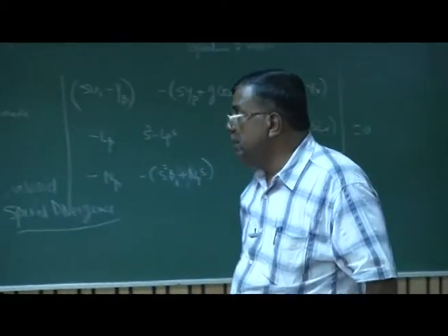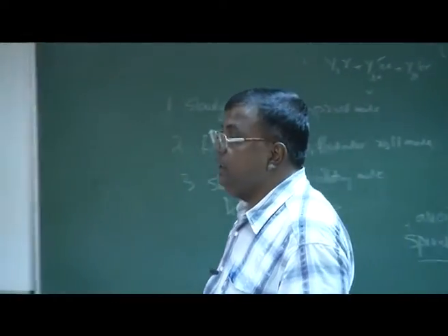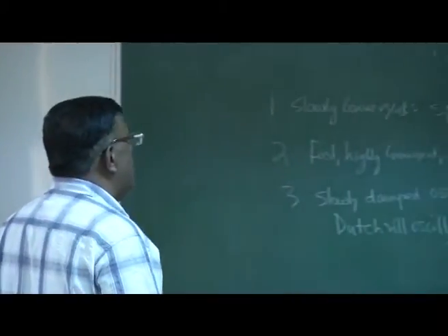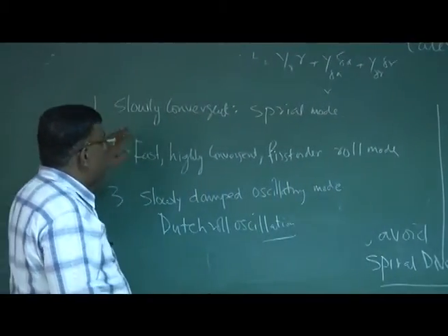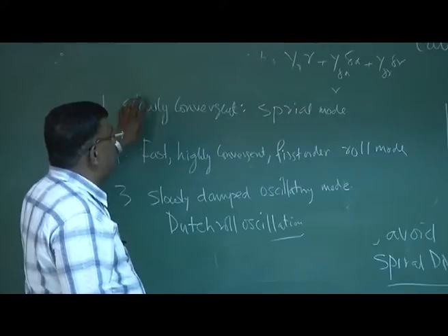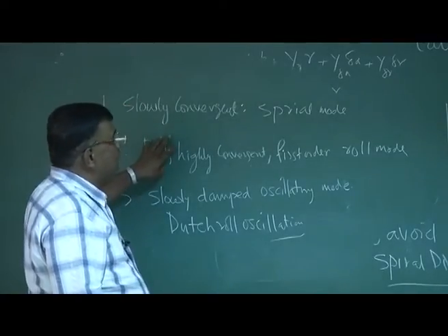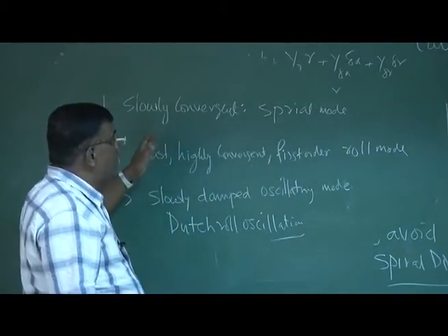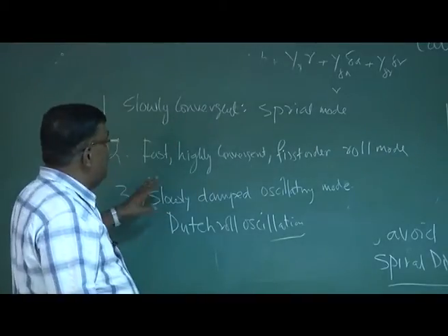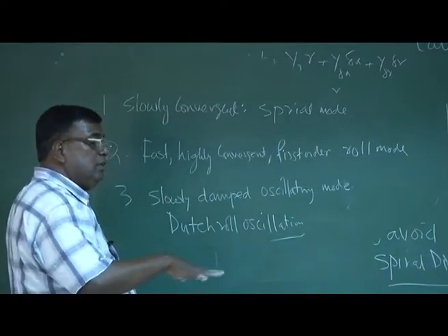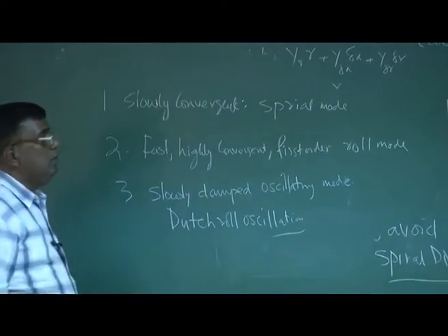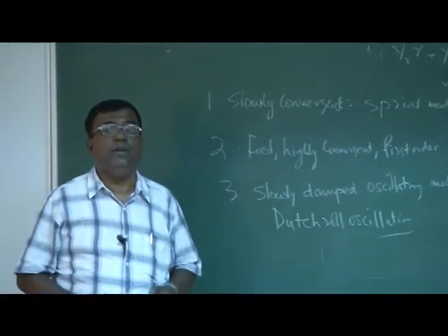So the airplane in the lateral directional case can get excited primarily in either of these modes or a combination of these modes, right? And that is why a designer needs to know the natural frequency, the time period, time to double, time to half. Similarly here, how much time it takes to go from one bank angle to another bank angle, and the oscillation, natural frequency of Dutch roll mode, to design the handling qualities of an airplane.